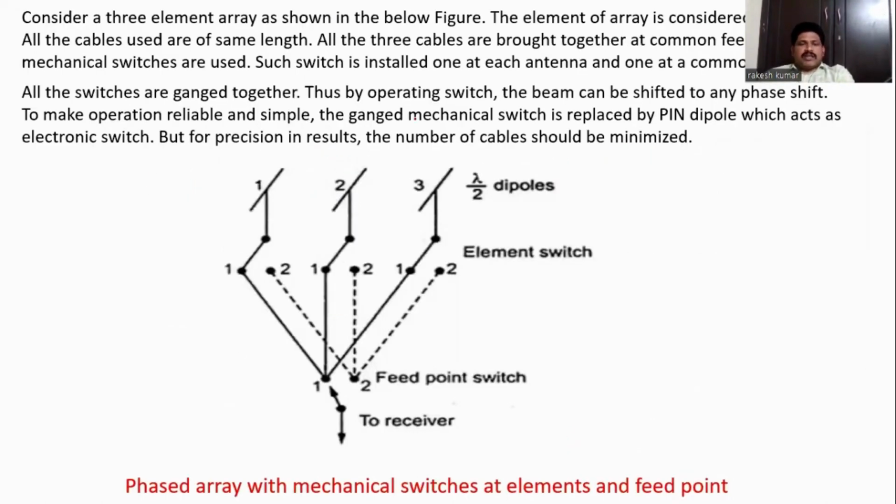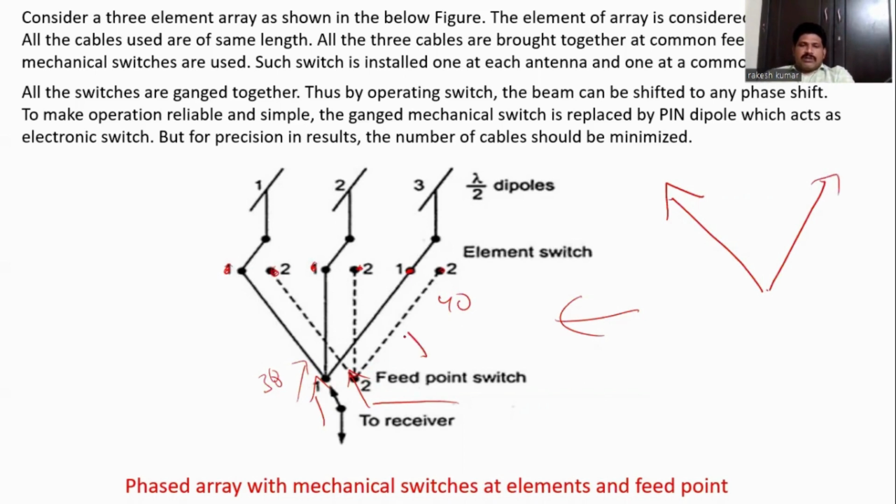Let us consider this is a phased array. Here, for example, let us say three antennas are there. This is one set. For this, they have fed with 30 degrees. Another set they have fed with 40 degrees. For some time they will connect the switch to this antenna, and for another period they will connect the switch to another antenna. So for 1 second it will radiate in that direction. Next, automatically the switch is connected to the next one, and it will radiate in another direction.